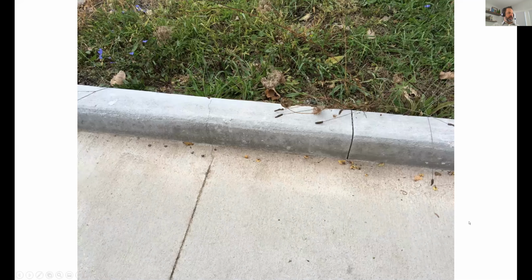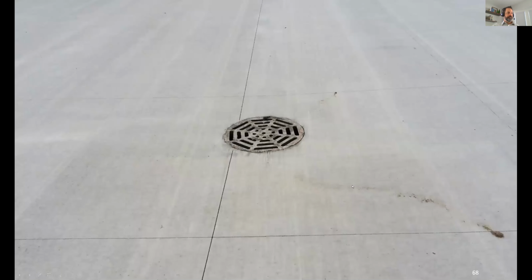This is that same project, different spacing, as Heather mentioned, in the curb than the parking lot slab itself. So there's another example of like a little closer, but still not the same thing. The concrete slab is going to dominate this little piece of curb, and it's going to crack all the way through. This cut is not causing anything to happen at that location.